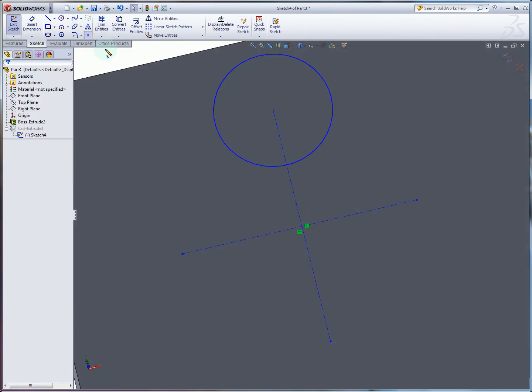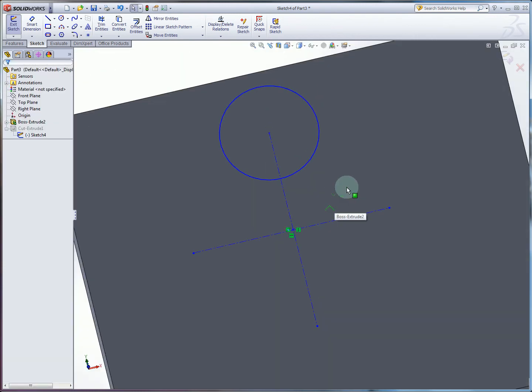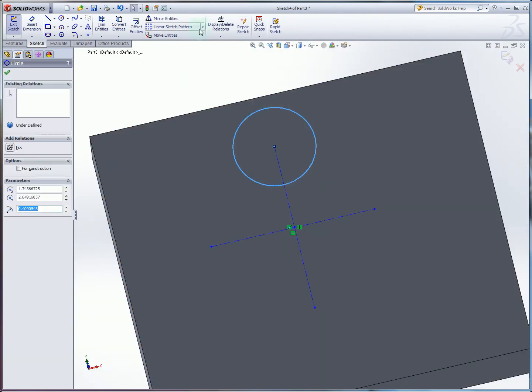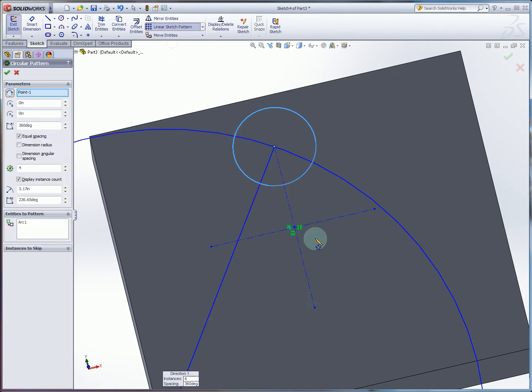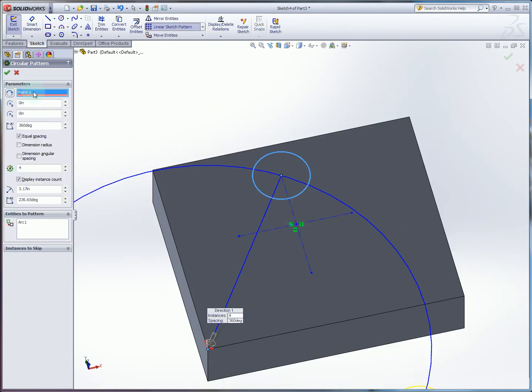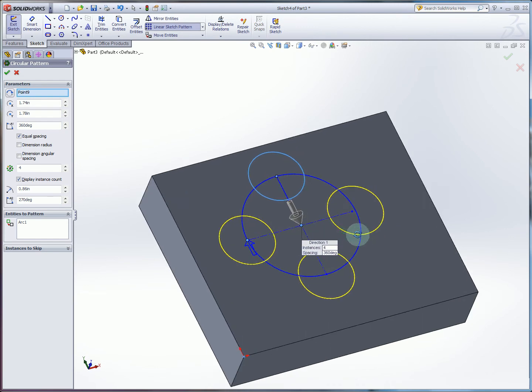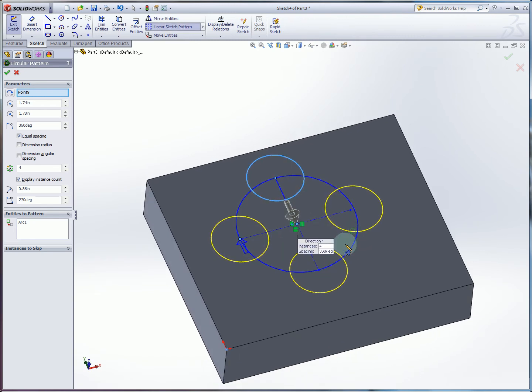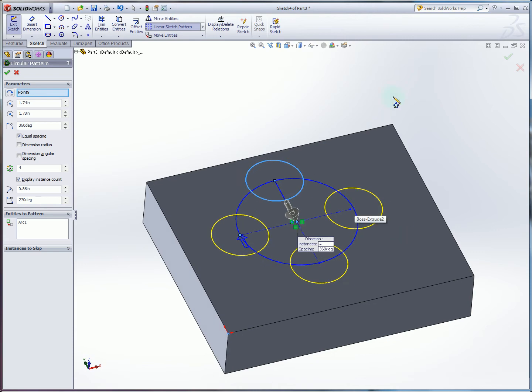But if I go into Sketch, I have a point, I have a center in my sketch already, so sorry if I place that correctly, I can just directly create this pattern within the sketch using either linear or circular sketch pattern, and I can choose as my reference that center point there. So you can see this is very powerful because I can sketch a center reference, and I don't have to worry about if I have a cylinder or an axis or anything else handy. Using essentially the same settings, the fill, we have the angle to fill, whether we want equal spacing, how many elements. So I could up this, for example, if I wanted more.